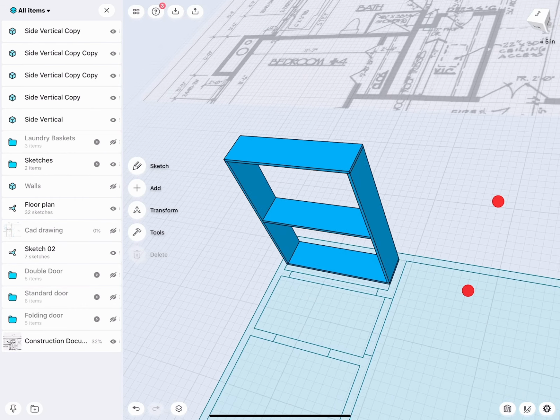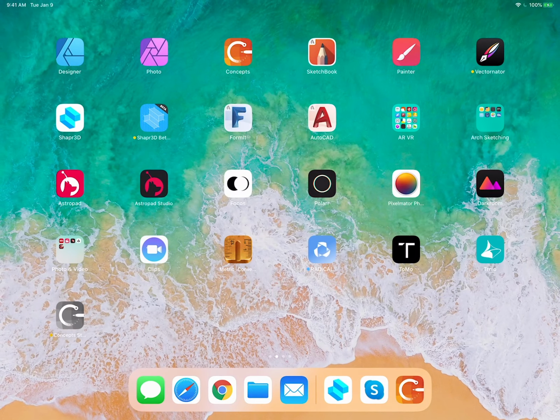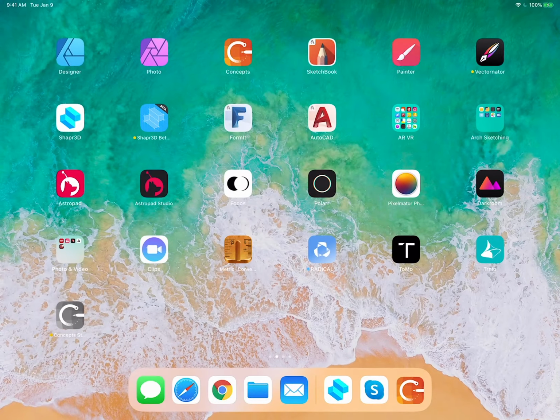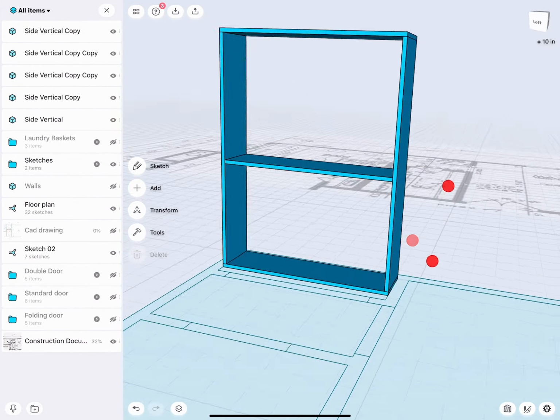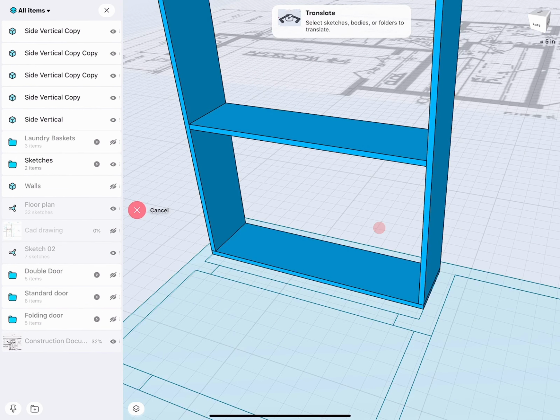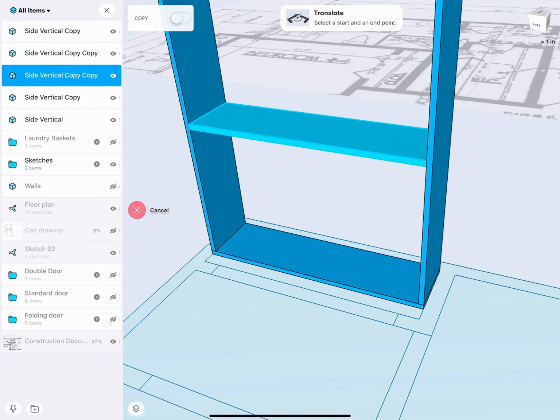Okay, so let's go back one more time here. So there's a 39-inch height. So how do we do this? Well, I did not do any sketch. I don't want to do a sketch. I just want to continue working only with the least amount of sketches. So I just work with the geometry as much as possible and use direct modeling. So one more time, I will use the move command and say from there, move it down to there.